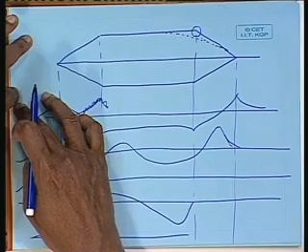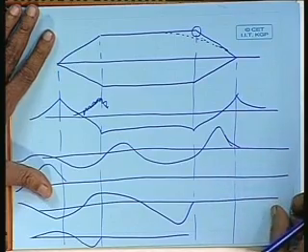You do not see those 4 waves and a pressure elevation here like this. So, what do you see? What you will see is a combination of all these wave systems, and a very easy mathematical solution is there for combining waves, which is called the linear superposition of waves. That is, as if they are just added, the resultant wave elevation will be a linear addition of all the waves together. You just put plus plus plus plus.